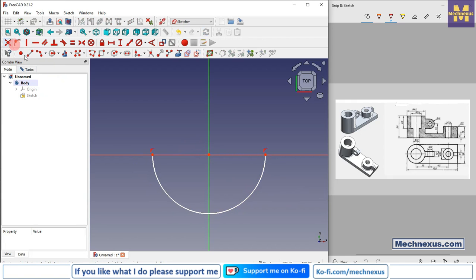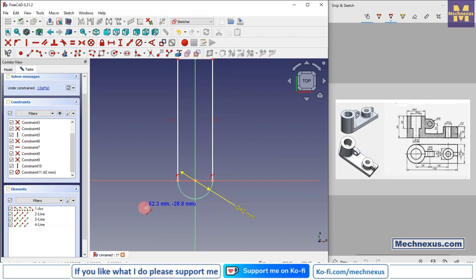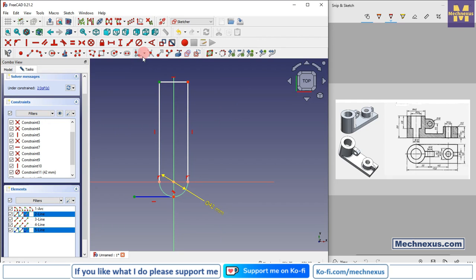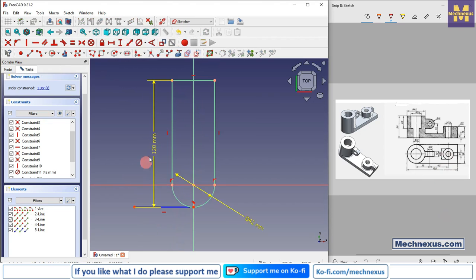and we will select this and click on the merge, and we will select a line tool, create a rectangle type of shape, and we will make it vertical. And here we will create a line. First we will make it tangent, and then we will trim it. So select this and add a construction, select this and this, add a vertical dimension of 120. So this construction line is not necessary. You can subtract this 21 radial dimension from this, and you can provide dimension to this line.